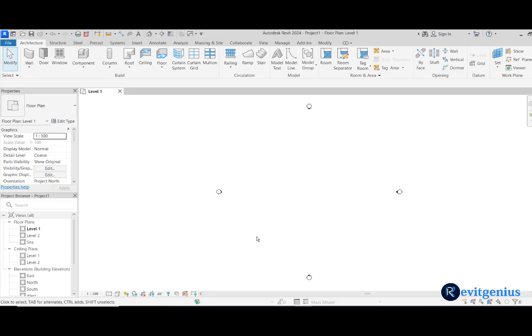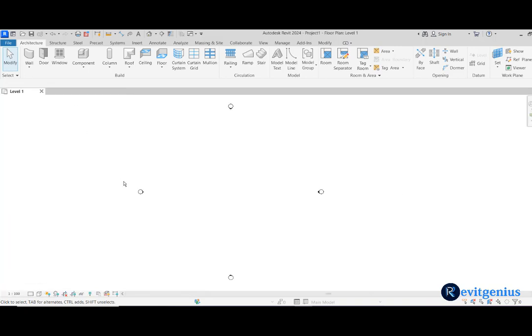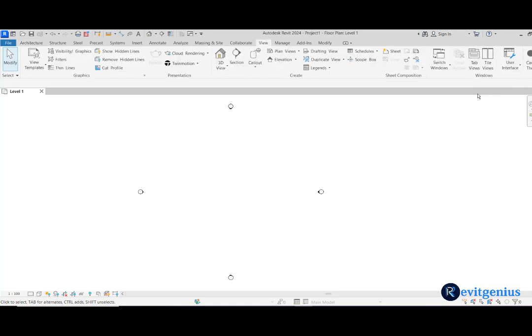We have 2 options on the drawing page. One is Properties and the other is Project Browser. Sometimes you may accidentally close these windows. Well, without them, we are literally paralyzed in Revit and cannot work. Therefore, on the View tab and from the User Interface section, we add the Project Browser and Properties options. That's easy.